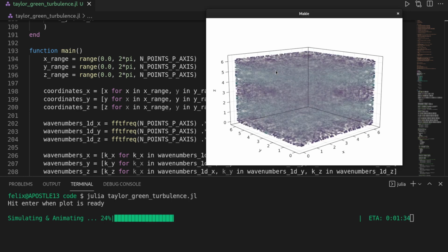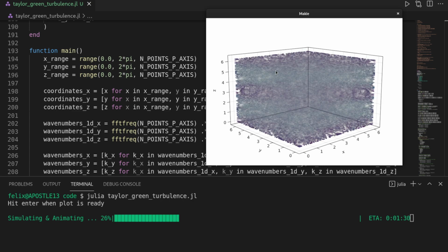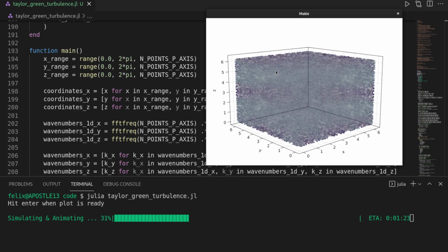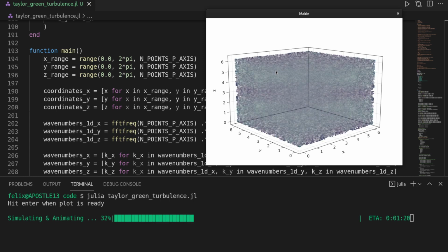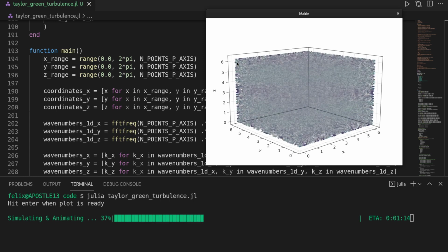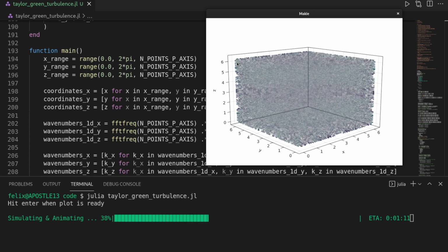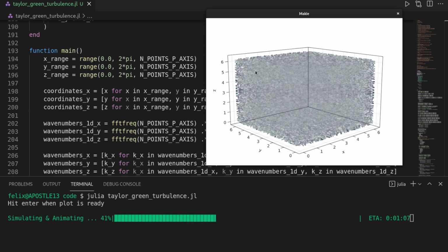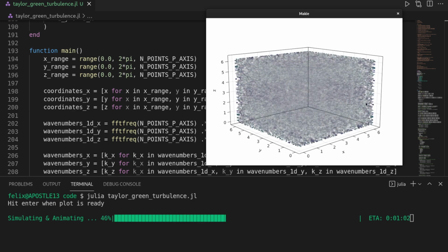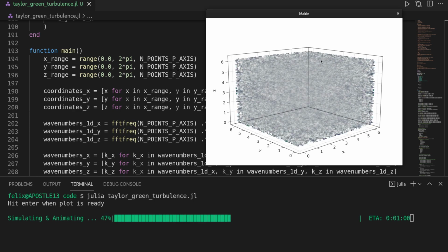And be aware that here we're using a resolution which is actually not sufficient for turbulence simulations at these particular Reynolds numbers. So if you have a more beefy machine, you should probably go to maybe something about 250 or higher. Anyways, we will still see some turbulence, although it's not that interesting to look at.